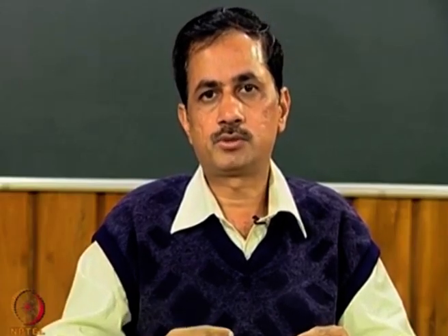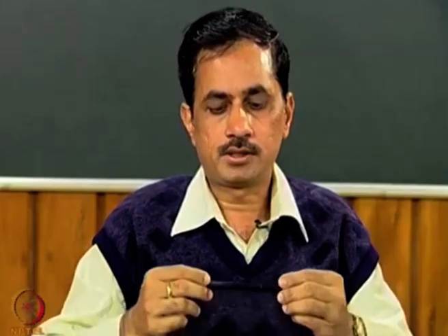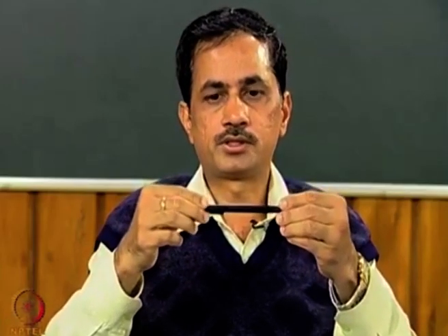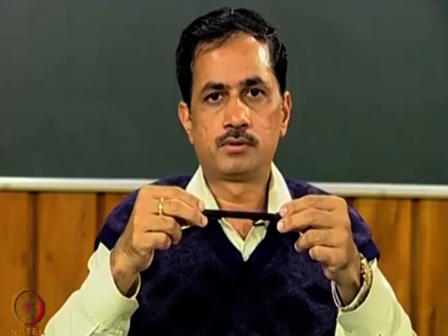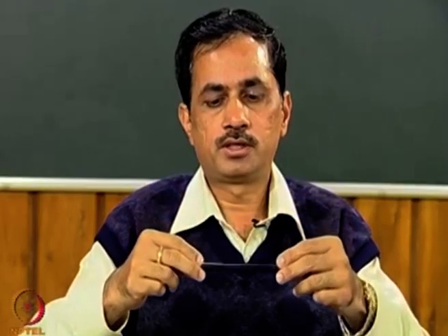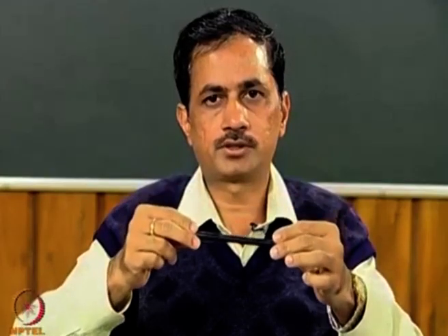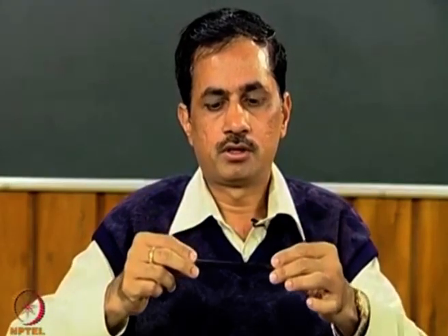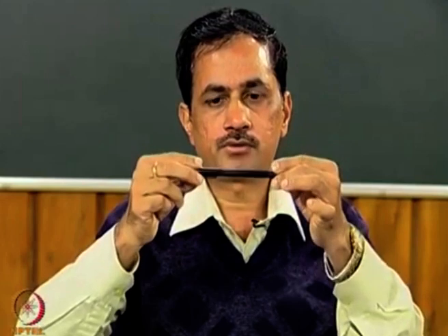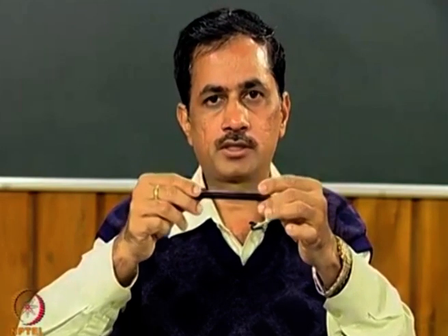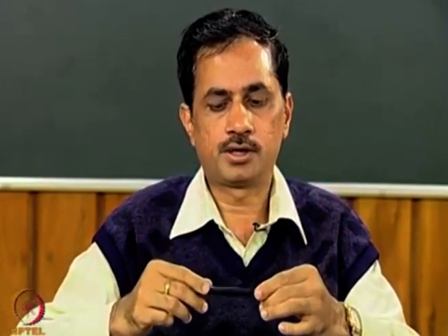So, first is the translational motion. Both translational motions we can consider simultaneously. If this is the rigid rotor, what is happening? This rotor has only pure translation motion in the x and y directions. It is not tilting, and it is whirling. Not only is it spinning about its own axis, but during that it is whirling.